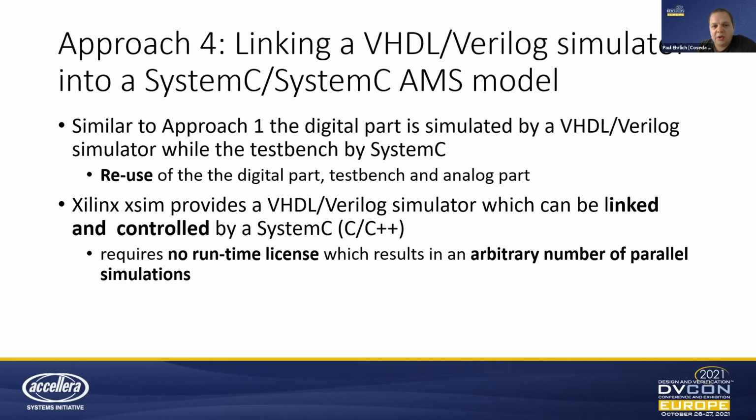So what we found which was capable of doing that was the XSI simulator from Xilinx. It has a C interface, so we can control it from SystemC. Every use case, so we are running thousands of use cases, is getting its own thread and runs against its own XSI simulator. And therefore we can spawn an arbitrary number of simulations in parallel, only depending on the number of CPUs our server machine will have.